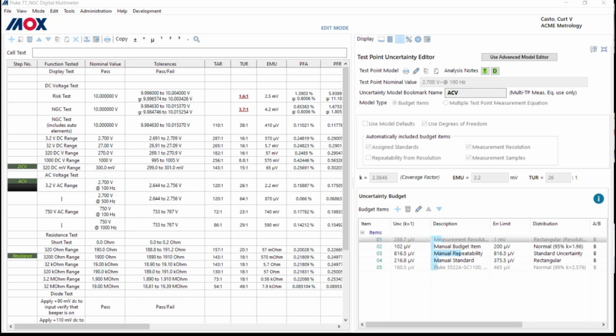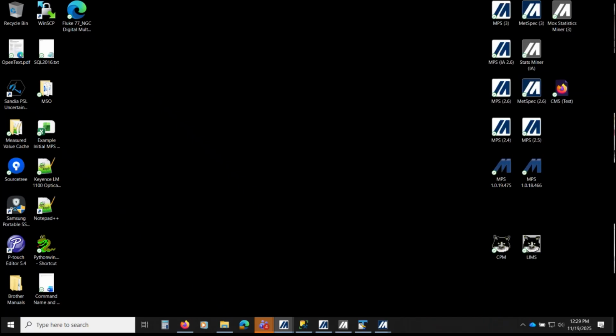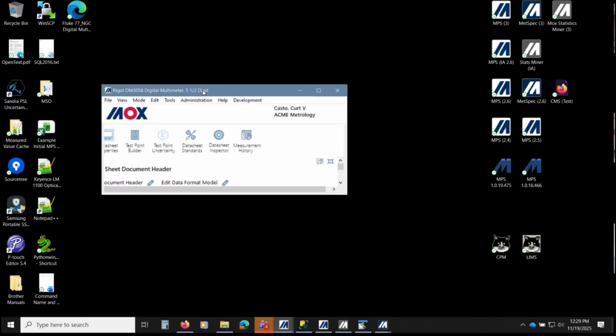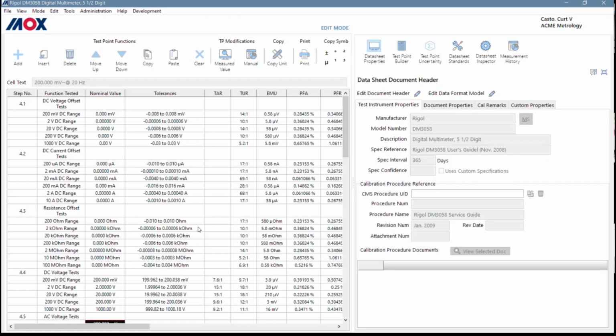And I also like this system because it's showing you here, in red, 3.7 to 1, 1.6 to 1. In my experience with other software, the technician had no clue he was 1.2 to 1, or even upside down. They're just taking data. But here, as they're going through it, they're getting highlights saying, hey, wait a second, you might want to pay attention to what you're doing here. And that's teaching your technicians about test uncertainty ratios and test accuracy ratios.